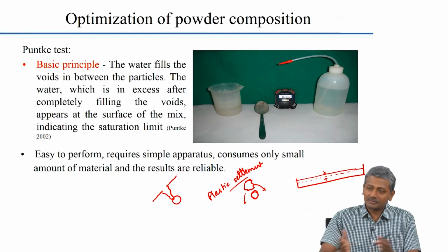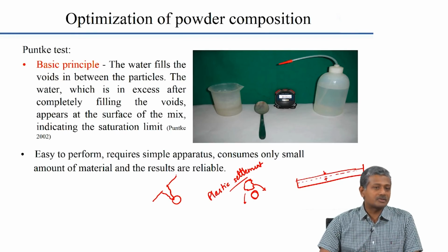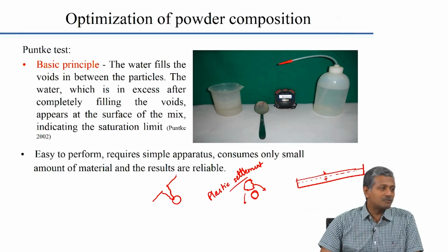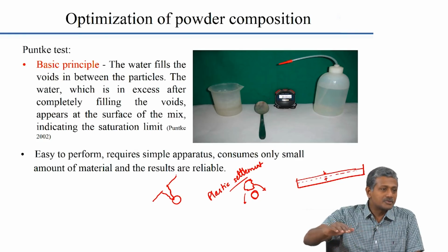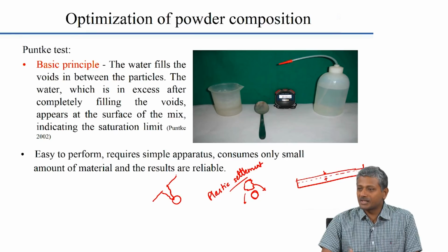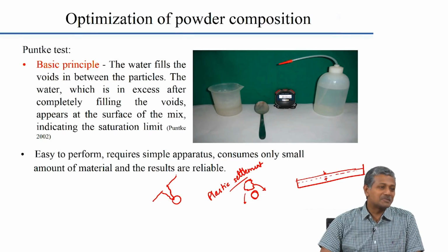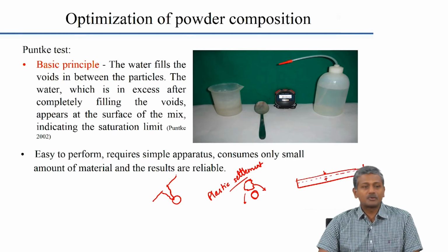He put into practice what he was teaching in class and made all the structural elements including columns, beams and slabs with SCC. Those were the early days that we were trying to work with SCC, and he realized that again, when high flowability SCC was used for the slabs, he started getting cracks. So, his house was an experiment that he was conducting to really get some real time data, and it worked out quite nicely. We understood that high flowability in slabs could be a dangerous thing.